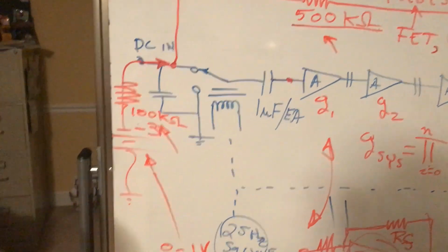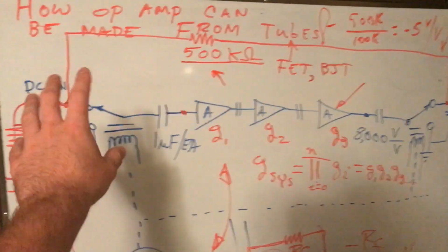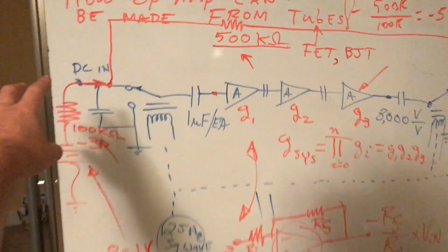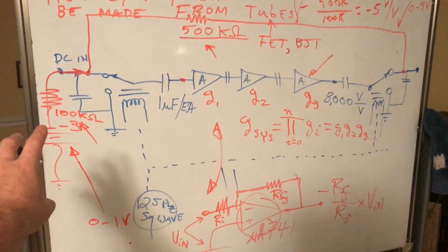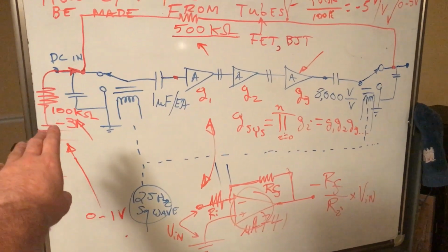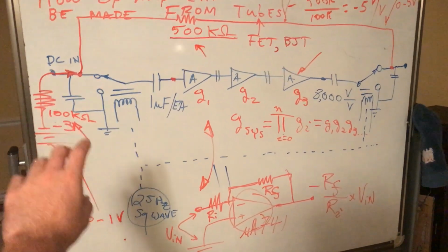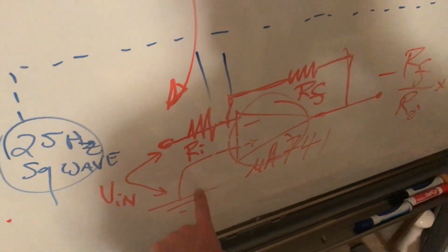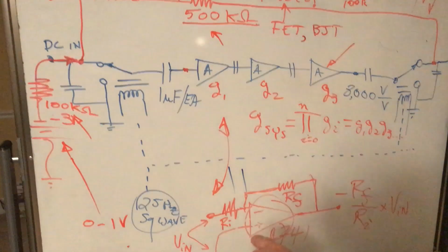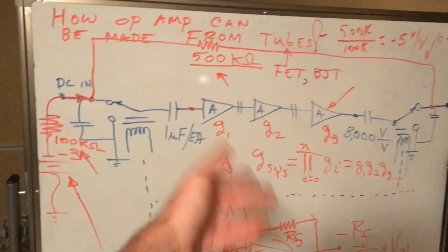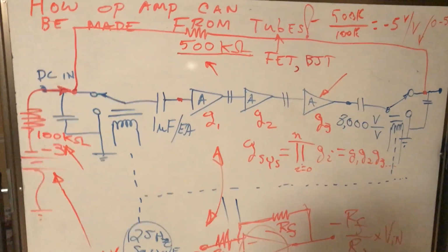If you can't do it one way, you can convert it from one to the other, do what you need, then convert it back. And I think this is a very nice example for how a classroom of students could build their own operational amplifiers in a day. No differential stage needed. In practice, this plus node mostly goes to ground, so actually this guy can do anything a regular op amp can do. You can just use negating ones and then adding to make a differential amp or an instrumentation amp. But I wanted to make this point clear.